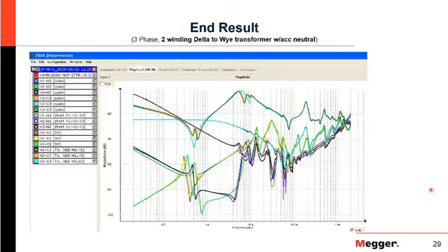And so remember, the actual device itself just did the same thing every time. It applies a voltage, a 10 volt signal at a varying frequency from 20 hertz all the way up to 2 megahertz. And then by changing our connections, shorting something out, grounding something out, we're actually getting multiple different responses for that particular transformer. And at the end, you'll get something like this for your fingerprint of a typical 2-winding transformer there.